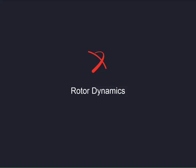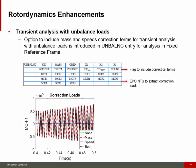Moving on to Rotordynamics. We've done some enhancements in Rotordynamics. In this case, it's a transient analysis with unbalanced load. Now it's possible to include the mass and speed correction terms to account for inertia and gyroscopic effects when you add the unbalanced mass. And those terms can have a significant effect depending on the rotor and the amount of unbalanced mass.